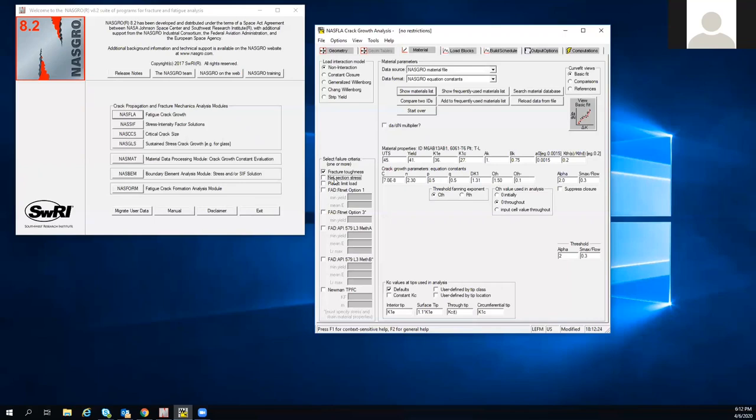So it will no longer flag a failure in the solution when it gets to that. Now, if you have something like a beam or a strut or a bolt that has a minimum cross section and it's a single point of failure, you don't want to suppress that check. You want to make sure that you're checking, hey, have I gone above what this is capable of withstanding from a strength perspective? So general good practice is to keep those both checked.